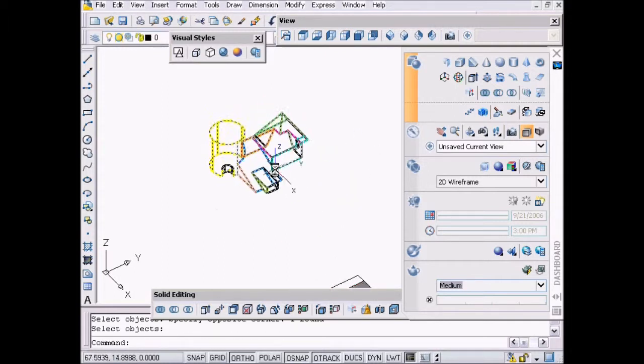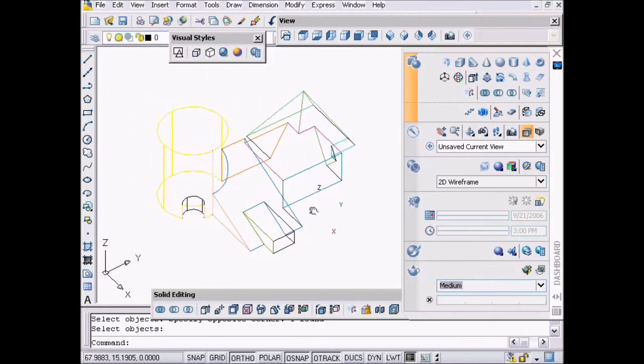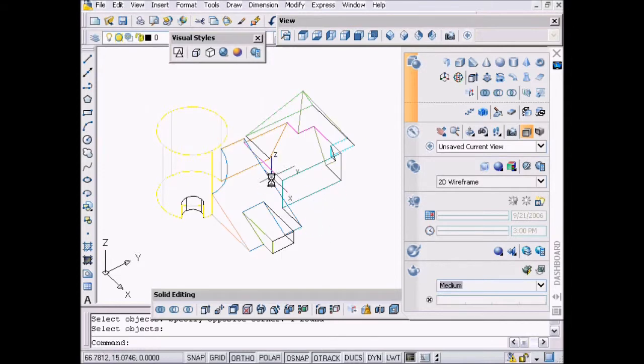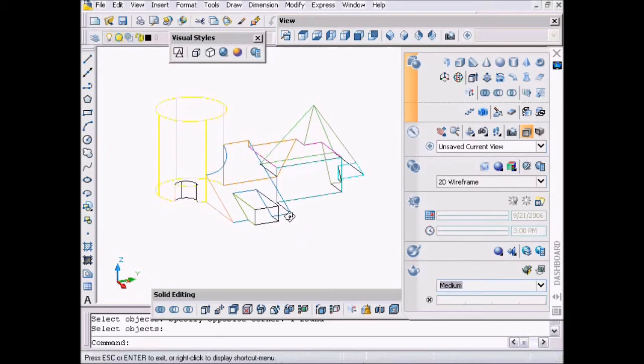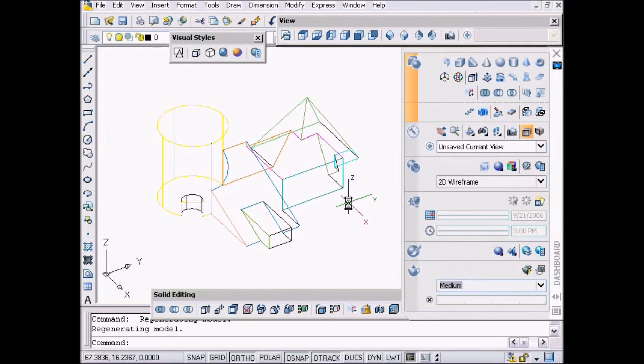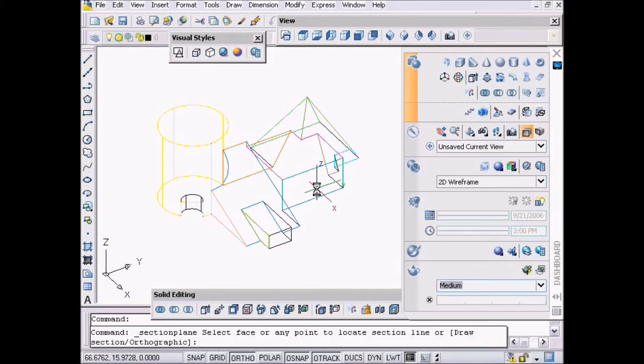Okay, so you can do them in 2D or you can do the section while you're in 3D. The nice thing is when you delete the section, the objects come back. Okay, and then these are all tools that we use to create the different geometries we're talking about here. We use a combination of any one and all of these tools, and the push, pull, and this. There's another one here called slice, which is very much like section. Okay, we'll get to that a little bit later, but section's a little fancier and newer. Slice has been around for a little while.